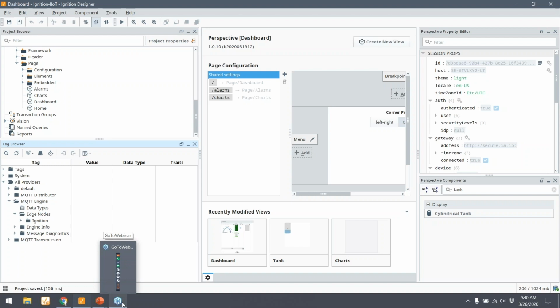So what we've got set up for you is Benson from Opto 22 has some Epic controllers and Rio that has connected to some data, so some legacy brownfield PLCs, as well as the Rio being brand new I/O and sensors, having that data publishing up to an MQTT server. And so what we can do here is have the central Ignition system connect to that same MQTT server that they're publishing to, so we can discover that information, turn it into tags in Ignition, and start being able to build dashboards very quickly with that.